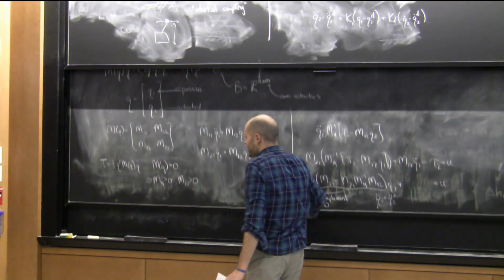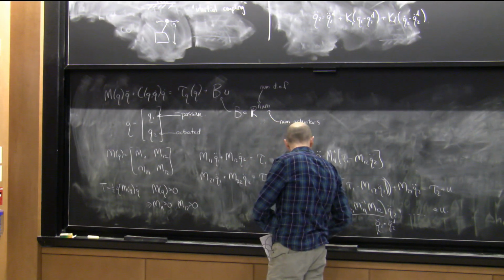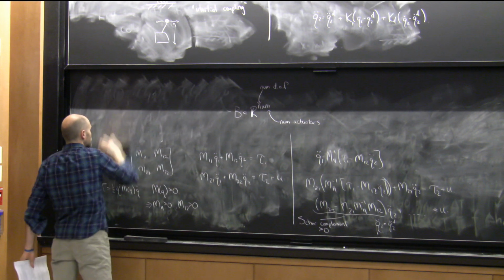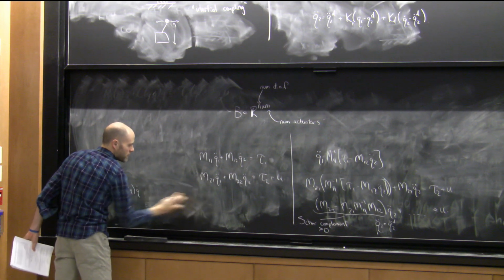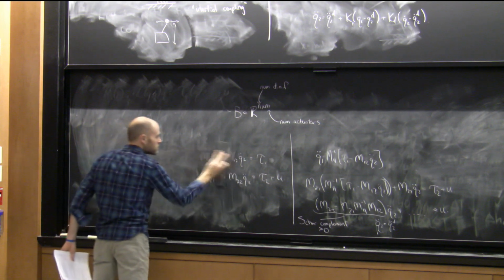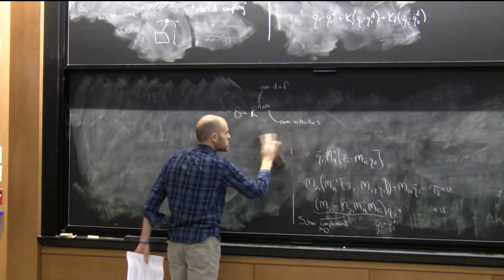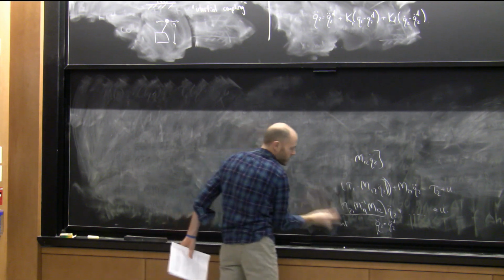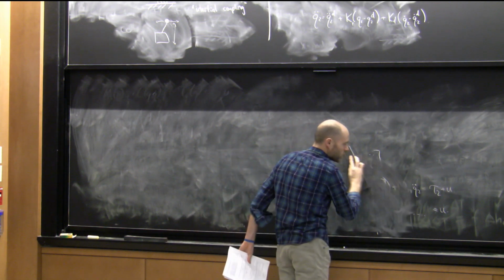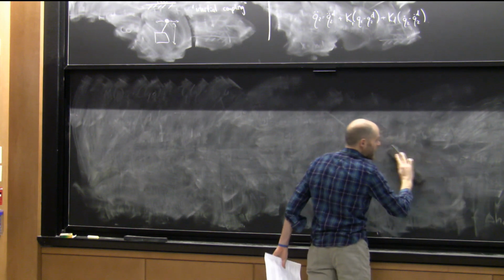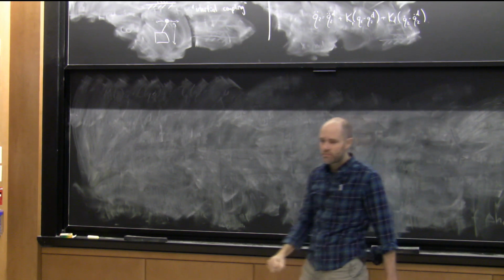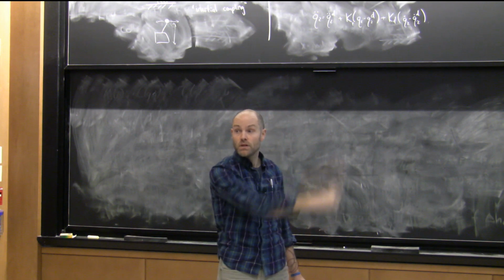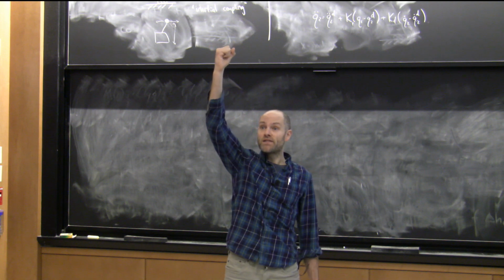So how do we use this? We're going to combine that now with Lyapunov to get a controller that'll swing the cart pole up to the top. And it's tempting to say, let's use the non-co-located feedback linearization, because if I'm going to try to control the pendulum, I'd like to drive that to the top, and that's the easiest route.